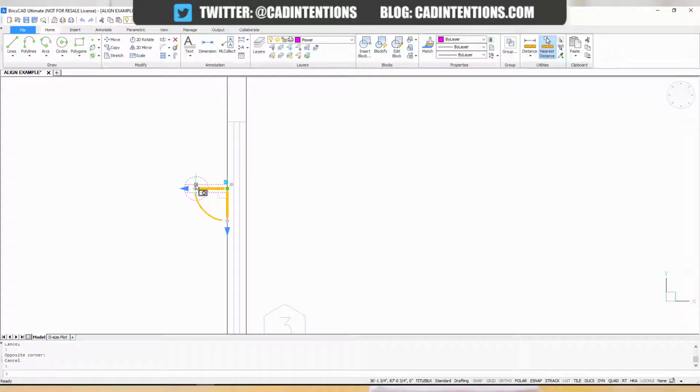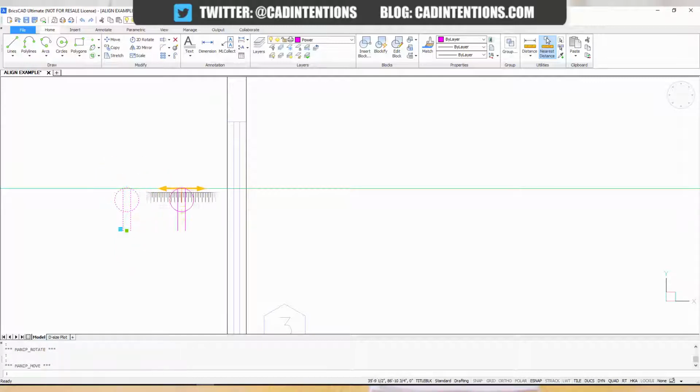So the next tip or feature I wanted to highlight is called the manipulator. By holding down on an object or entity with the left mouse button for a little longer than you normally would, you can bring up access to the manipulator. It won't display until you've released the button, but from there you're able to quickly and accurately move, copy, rotate, scale, or even mirror your objects just by clicking parts of the little manipulator icon, as you can see here.